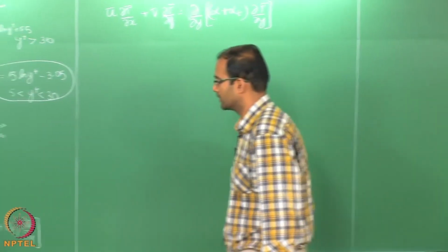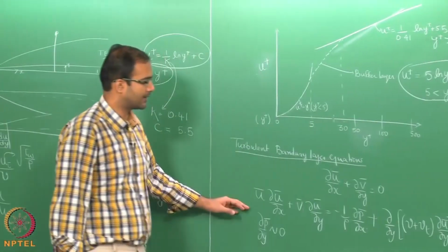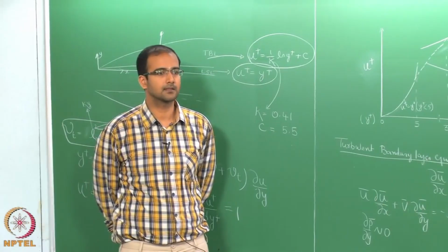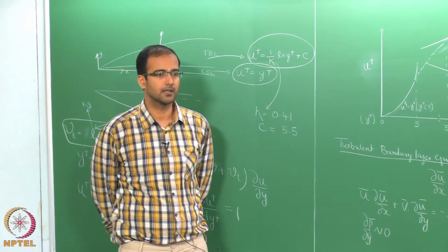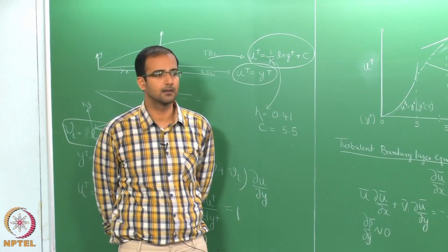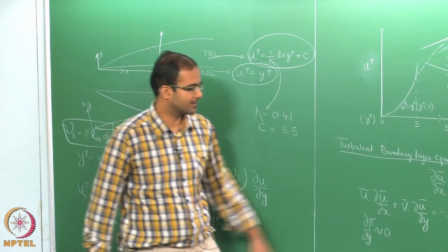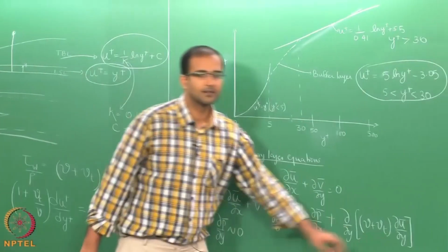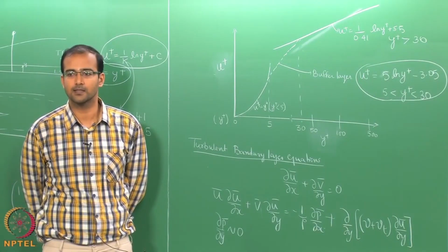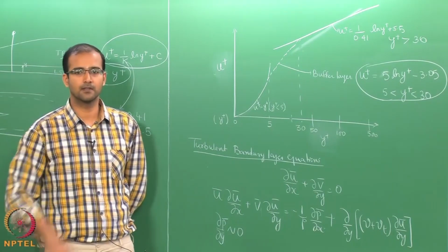Well, again, do you think that we can find analytical solutions to this, like the Blasius solution? It looks that we have simplified the RANS equation for the boundary layer, but the major problem is nu t. It is not a thermophysical property, we cannot assume that to be a constant, and wherever Blasius has used nu, we cannot replace that with nu plus nu t.